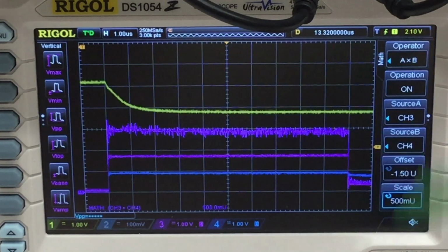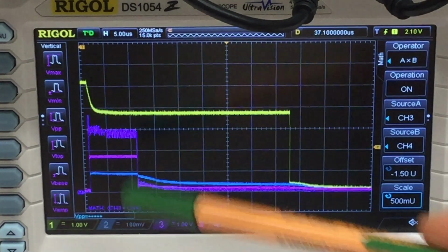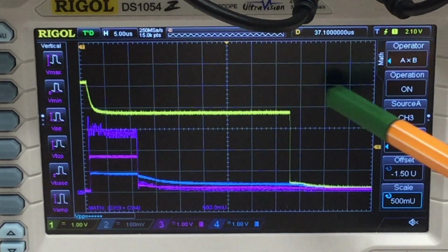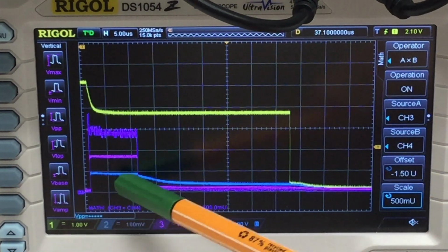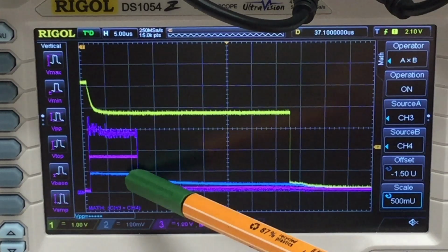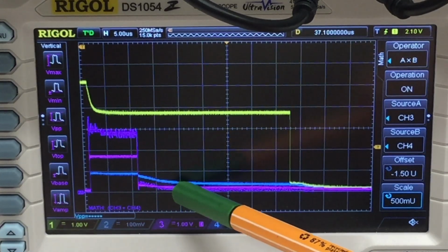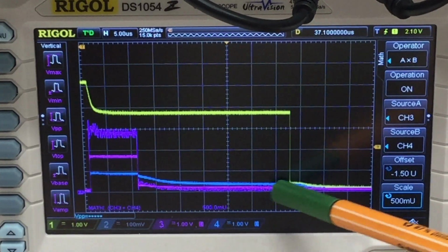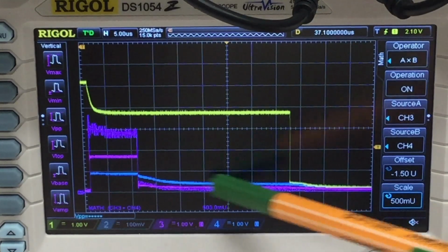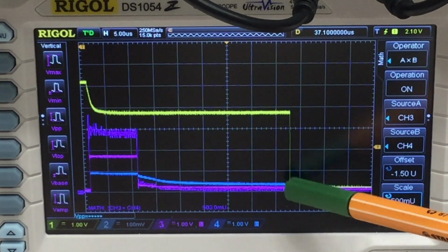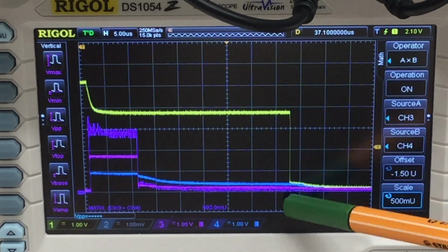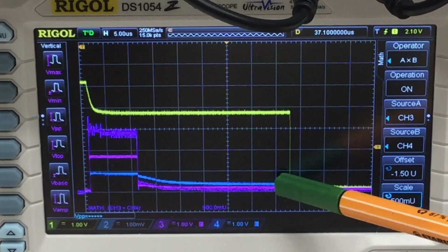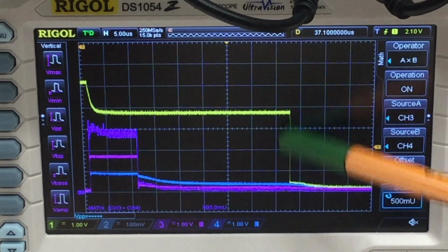It stays a little bit up. And further down the timeline, here we switched on, you see that the voltage across the gate is only slowly creeping down and still staying above 0. And only when the TRIAC switches off, it truly returns to 0.